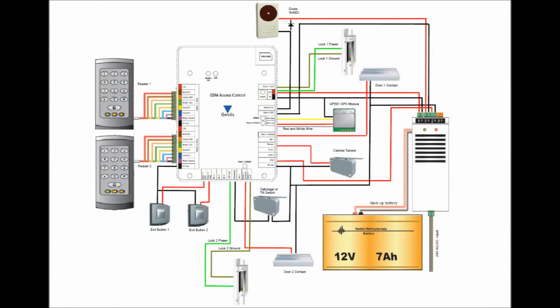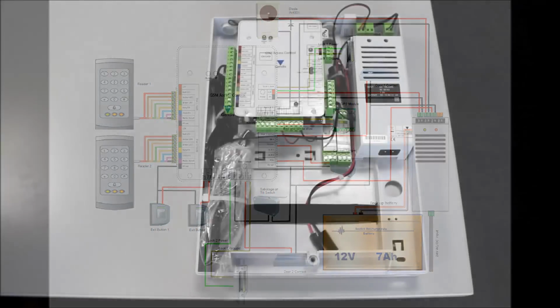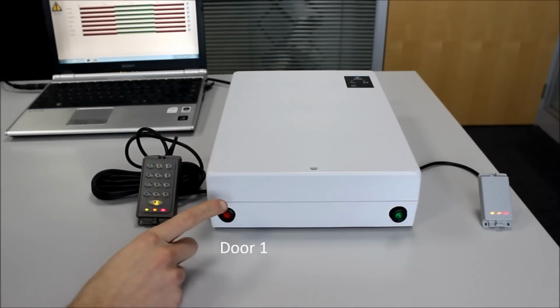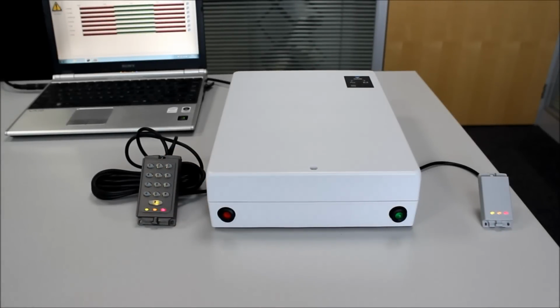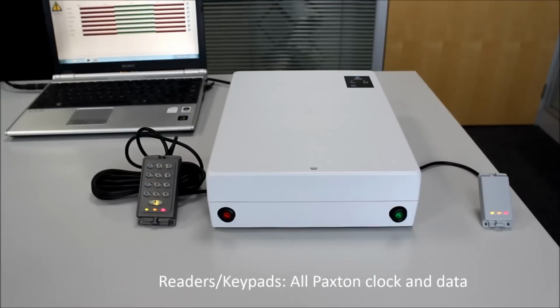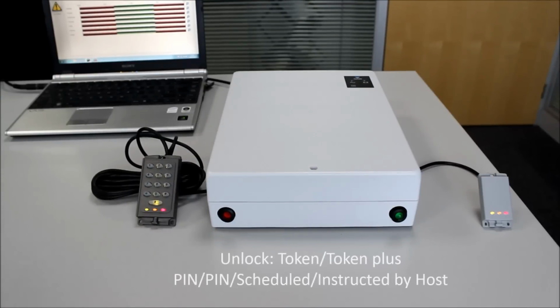Each single control unit, such as this demonstration model, can control two separate doors. It is compatible with all mag locks and lock releases, but in this case I will wire up two LEDs to represent the two different doors. So this red LED will light up for a period at which door 1 is unlocked, and this green LED will light up for the period at which door 2 is unlocked. Now the system works with Paxton proximity or touch lock readers and keypads, and Net2 and Switch 2 proximity tokens.